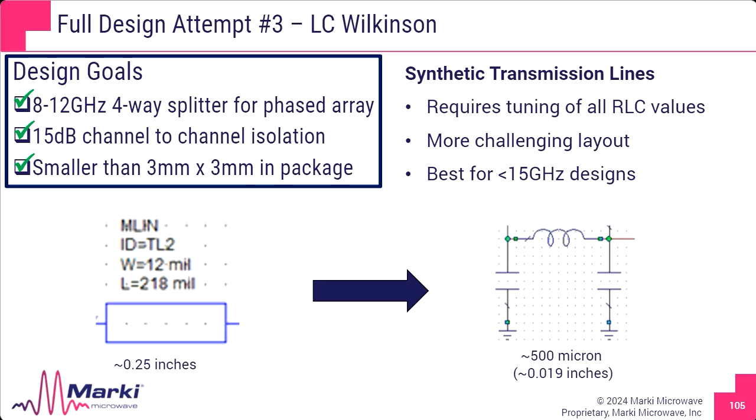This is a significantly more complicated design to achieve. It requires tuning of every single inductor, capacitor, and resistor. The layout is significantly more challenging, and 15 is probably pessimistic. For maybe 20 or so gigahertz designs is where this is best.